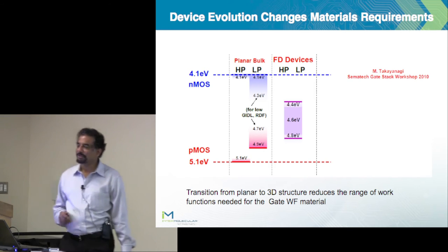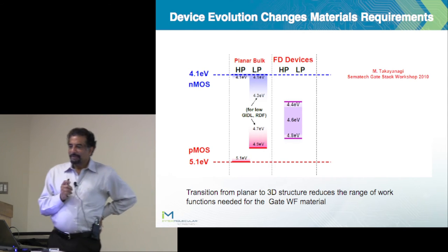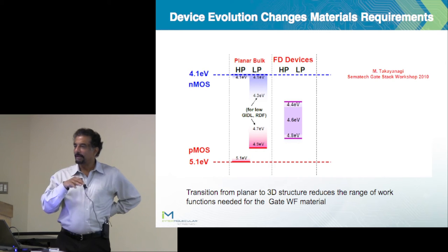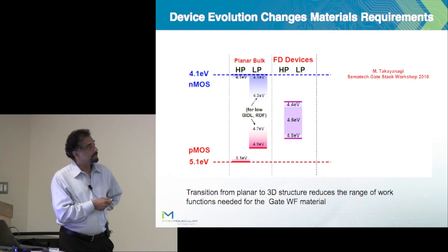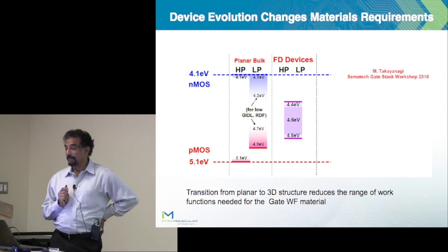Now let me come back to this. I talked to you about the silicon interlayer formation, right? What people noticed was that they'd start off with some oxide at the interface, and the moment they put the metal gate on and went through an anneal, the interlayer thickness would increase. This is showing the partial pressure of oxygen and the temperatures, that even at 450 degrees you could get like 30 angstroms of oxide growth.